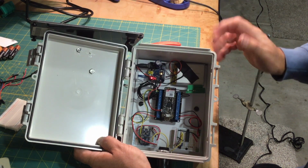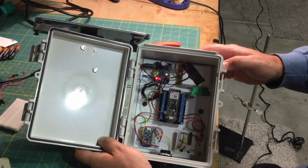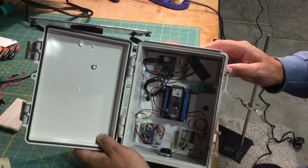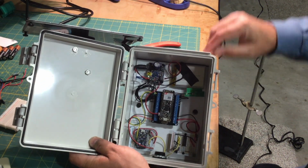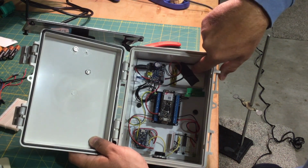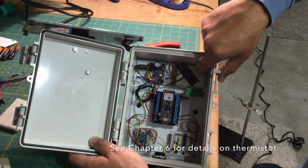Of course, if I'm going to store this for a few days, I can store it in the light. You know, I could actually put this outside to help that solar LiPo charger charge that LiPo battery. You'll notice that I have a thermistor attached to the battery to keep it from charging if the battery should get too hot.